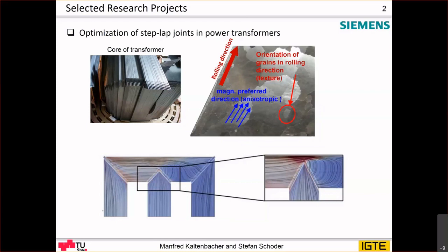So you have to take into account this anisotropy, and in addition, as you know, and we will also discuss this, the relation between the magnetic field intensity H and the magnetic flux density B is hysteretic. So when you consider hysteresis, and in this case it has to be a vector hysteresis operator, you can also compute hysteresis losses accurately.